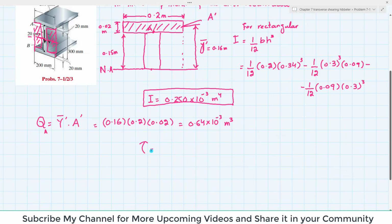So you can put it in this formula to get the shearing stress at point A. Shearing stress is equal to V into Q divided by I into t. V is given as 20 kilonewton, 20 into 10 to the power 3. Q is 0.64 into 10 to the power minus 3. I is the moment of inertia of the whole beam, which is 0.250 into 10 to the power minus 4, and t is the thickness.